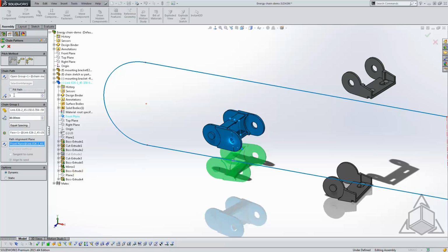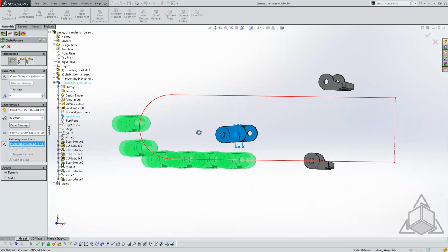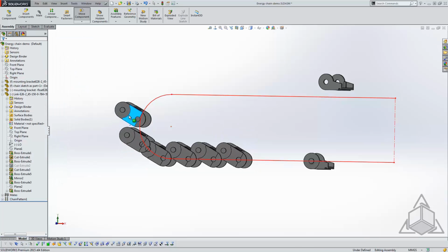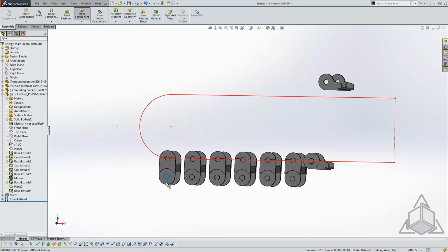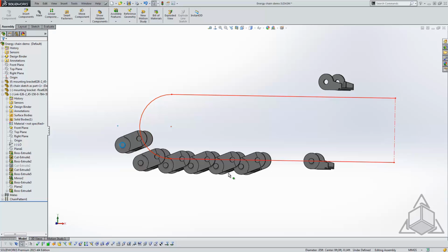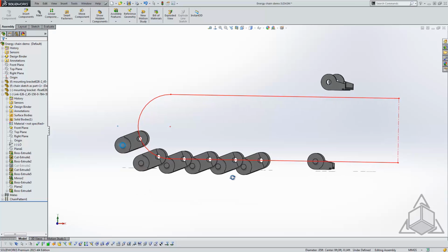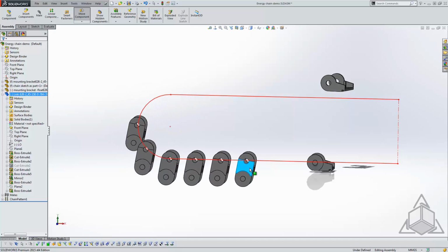Now I've only got one instance set to a spacing of 80 millimeters, so as I index this up we'll see 80 millimeters, we get another one, but we do see that it moves along that path. All right, so it travels along that path, and if I say OK to that, we see that we get motion, so very much like a path mate, but we get motion in all degrees of freedom. It will rotate along that circular reference that I gave it, and that circular reference can also move along that path. All right, pretty neat.